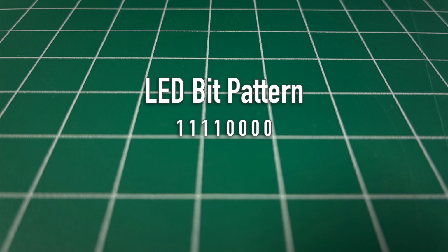I'm including a link to an Addendum video where I go over binary and hexadecimal numbers in detail, but here's the very short version. Any 8-bit binary number can be broken up into 2 4-bit binary numbers, so 11110000 becomes 1111 and 0000. And each of those 2 smaller numbers, which are called nibbles by the way because they're tiny bytes, can be replaced with the equivalent hexadecimal digit from 0 to F. So 1111 becomes F and 0000 becomes 0.